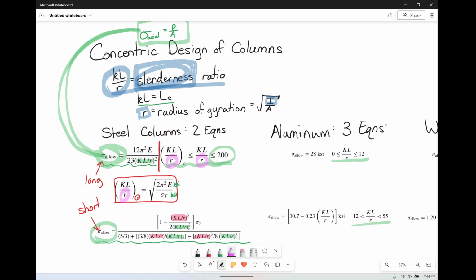Again, if you're talking about a rectangle shape, it's not really that hard. You'll have an A, you'll have like a 1.5 A. And you can calculate the area of the shape and the moment of inertia in terms of one letter and you'll be fine. But a W shape, that's a whole different story.